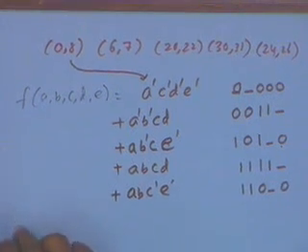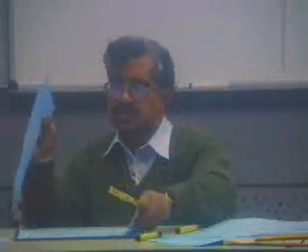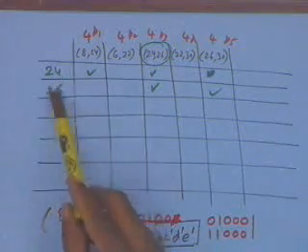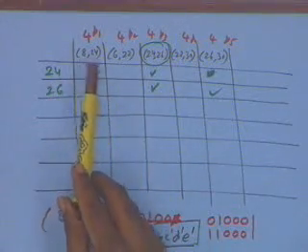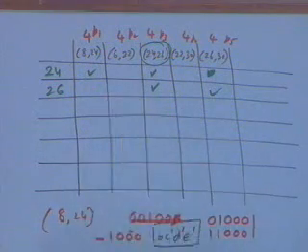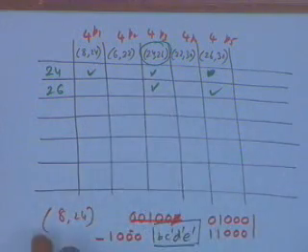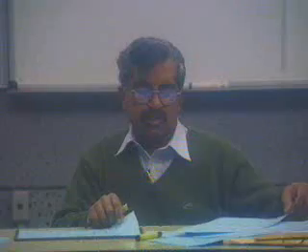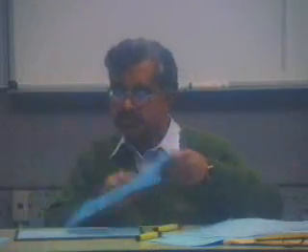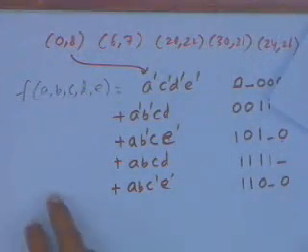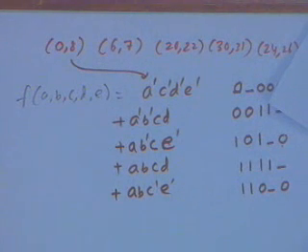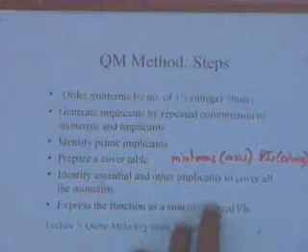24, 26 was the one that was chosen in this process. I had to cover 24, 26. I can cover by using both P1 and P5 or just by using P3. And this is the expression that I formed and chose the one which is the lower cost, which is the P3 is the lower cost one. And so that will be the minimal expression. And now what we have done is, this is the last stage. The step. So now I express the function as a set of prime implicants that have been chosen.